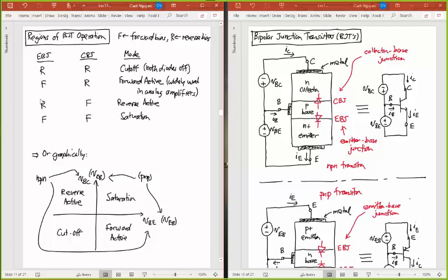Okay, I could do the opposite thing. I can reverse bias my emitter base junction, and I can forward bias the collector base junction. And so again, which is which depends on the doping concentration. The emitter is the one with the highest doping there. But if I do this, the transistor will still work. You can make it work upside down. It just won't work as well as the forward bias direction. And so what we're telling you right now is that this transistor is not quite symmetric, but it'll work in both directions. But you don't want to use it in the bad direction because its properties just aren't going to be very strong. You're not going to be able to get as much amplification. You're not going to have as wide a bandwidth in the eventual amplifier that you're trying to make.